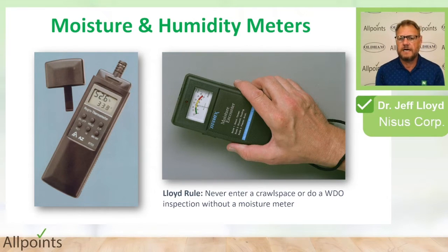When you do anything with fungi, or I would suggest any wood destroying organisms, make sure you have a wood moisture meter. This particular one I like, the Tramex, and there's a cheaper one made by Ryobi. These are capacitance meters, which I prefer to the pin type, the conductivity meter, and I like these because they can actually measure wood moisture content behind sheetrock, so you can scan a wall relatively easily and non-destructively to determine what the wood moisture content is behind that sheetrock.